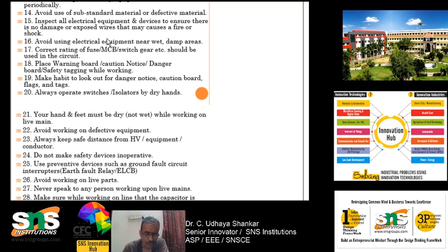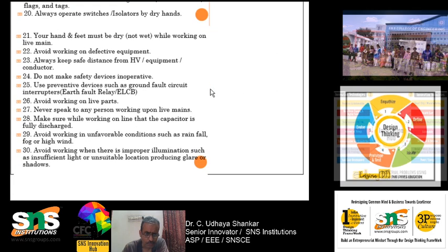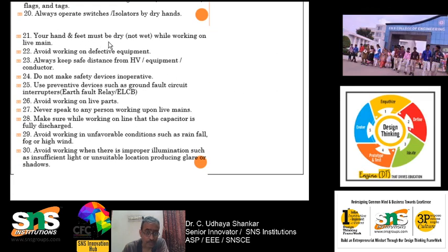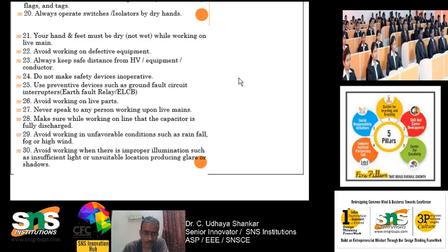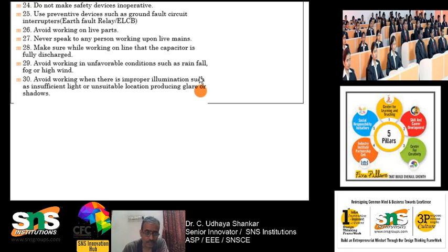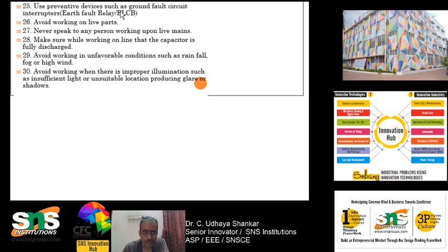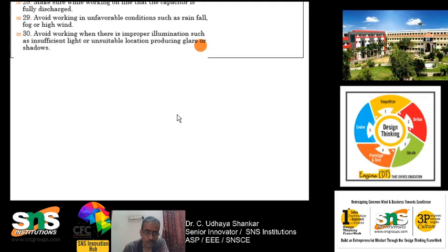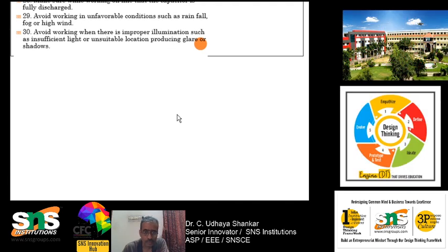So, and also like this many different safety aspects have to be followed, and your hands and feet must be dry. It should never be wet. Okay, very important thing. And while working on the live mains, avoid working on defective equipment. Always keep a safe distance from the HV, that is high voltage, and do not make safety devices inoperative, and use preventive devices such as ground fault interrupters, etc. So never speak to any person working upon the live mains, and make sure while working on the live line that a capacitor is fully discharged.